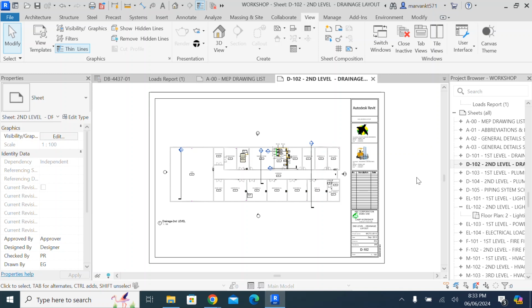But sometimes, for example, you already have the design drawing in AutoCAD and you want to develop the BIM drawing in Revit. So you can just link your CAD file, but by linking the CAD file you can use it only for reference purposes. That is not the BIM file. Later on, according to that, you can place your elements and route your duct, cable tray, or whatever, all the services. So you can use the CAD file as a base drawing or reference drawing for your BIM file. You can create without that also, but if you have it, you can do it.